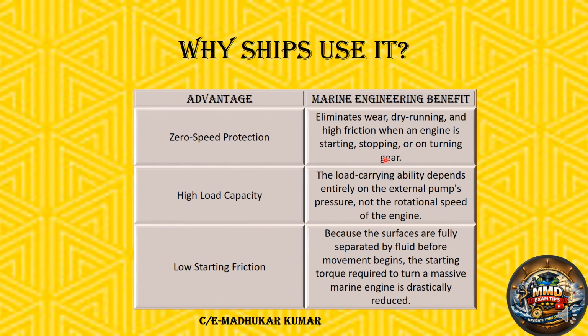So we can easily run and turn the engine because we know a separation already exists, since the lube oil pump was started earlier. That's why we say to start the lube oil pump and the lubrication well before starting the engine, at least 1 or 2 hours. So there is no chance of any contact.